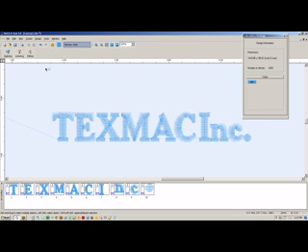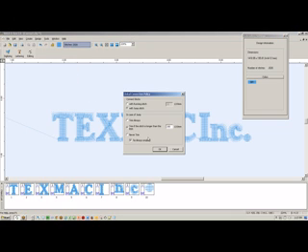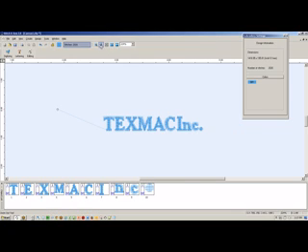what the Stitch and Sew is trying to do, and that's under what's called connection policy. If we go to design and connection policy, we're saying that you're going to cut if the stitch is longer than 2/10 of a millimeter, or in other words 2 centimeters apart, almost an inch. Well, that's kind of crazy. That means that it's not going to trim unless I move at least an inch away. If I click, now you can see that it added some scissors there.